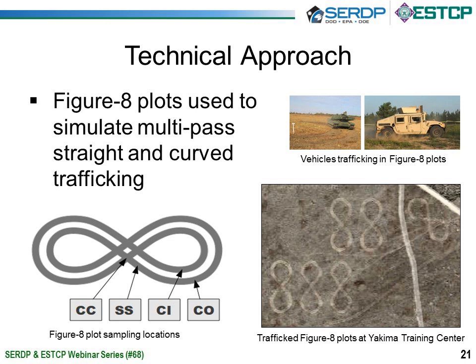Multi-pass trafficking field experiments were carried out on all 4 previously mentioned U.S. DoD military training sites. At each site, a heavy tracked vehicle, such as an M1A1 tank or equivalent, which is approximately 50 to 60,000 kilograms, and a light wheeled vehicle, normally a Humvee, in the range of 3,000 to 4,000 kilograms, were used, except at the Yakima Training Center, where there were no tracked vehicles, and we used a heavier 15,000 kilogram 6-wheeled tanker fire truck for the heavy vehicle.